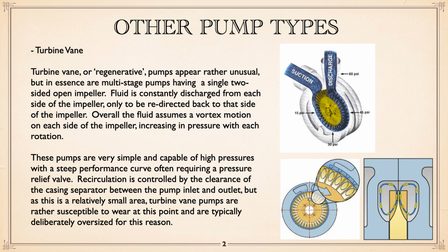Liquid comes in, water in basically is carried around that passage. Now, if you look at the cutaway in the bottom right-hand corner, the water is struck by the impeller, which spirals it out, and then it circles around. It's speeded up, of course, so energy is provided, circles around, slows down, picks up pressure, and then hits again, comes around, same thing. So it does a collection of these loops as it turns around, and each time it's caught by the impeller, the speed is increased, and each time it's diffused, the pressure is increased.